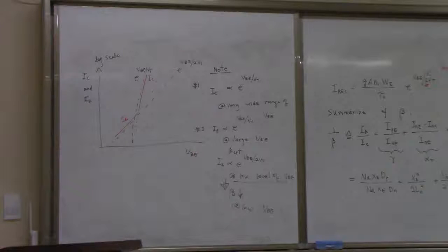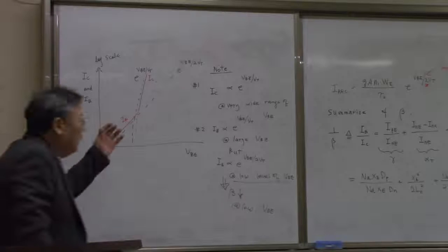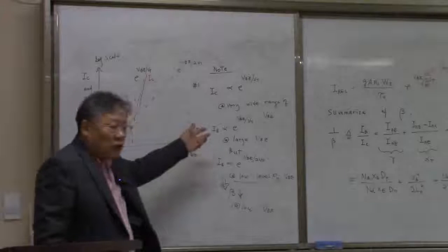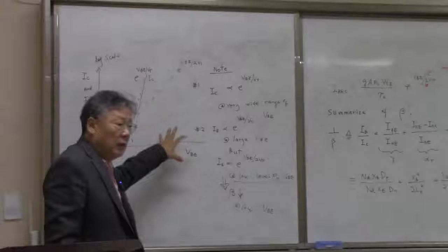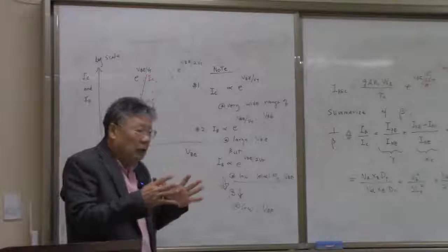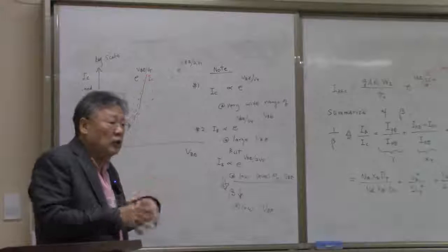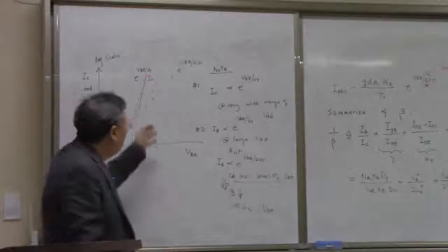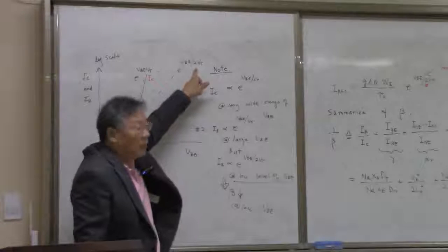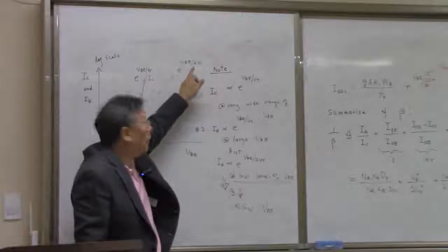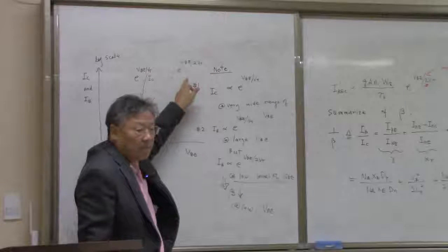Okay, so from this figure, what we can see is that at very weak input voltages, the bipolar transistor is not going to work well because the recombination at the space charge region is going to dominate. And then that recombination current is going to have a factor 2 in front of the VT here.